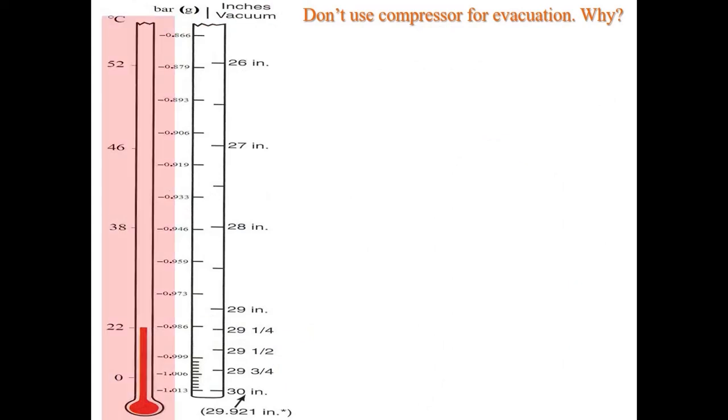This illustrates the ambient temperature, and this shows the water vapor pressure at that temperature in inches of mercury vacuum. For this explanation, I will use inches of mercury as the unit of vacuum pressure. In this context, 0 inches of mercury represents atmospheric pressure, and 29.92 inches of mercury represents perfect vacuum, which cannot be achieved on Earth regardless of the vacuum pump used. Whatever pressure unit is used, the basics remain the same.